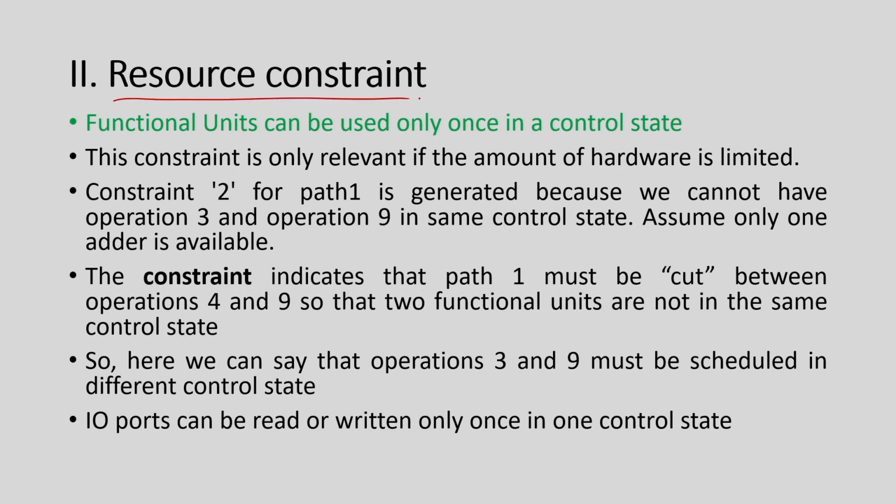As I clarified earlier, if there are say 20 addition operations, and if you schedule all 20, you need 20 adders. But it may be that you do not have 20 such adders available, so you have say 10. So, you have to cut the behavior such that in every state there are at most 10 operations. Basically the constraint says that you can only execute some operations in one state as long as it satisfies the resource constraint.